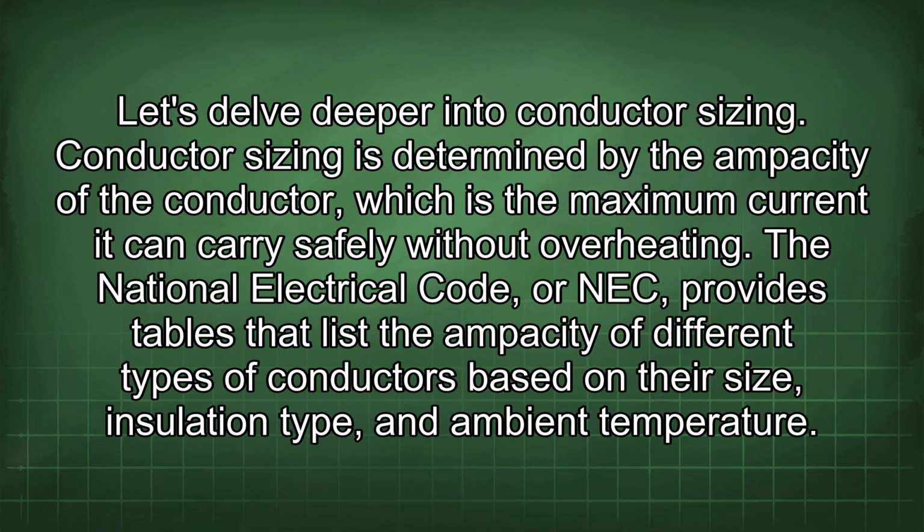Let's delve deeper into conductor sizing. Conductor sizing is determined by the ampacity of the conductor, which is the maximum current it can carry safely without overheating. The National Electrical Code, or NEC, provides tables that list the ampacity of different types of conductors based on their size, insulation type, and ambient temperature.